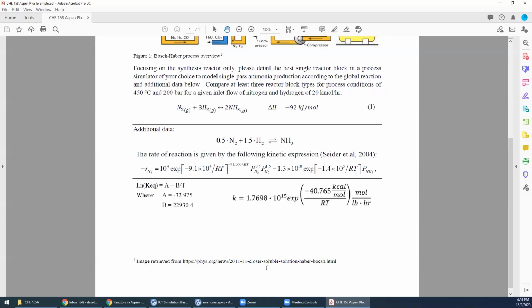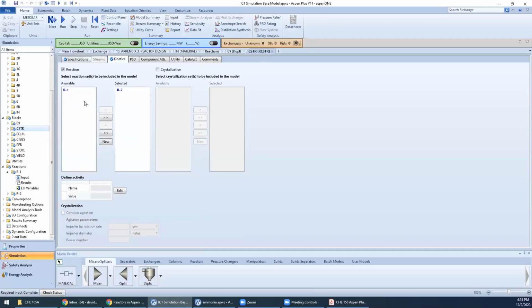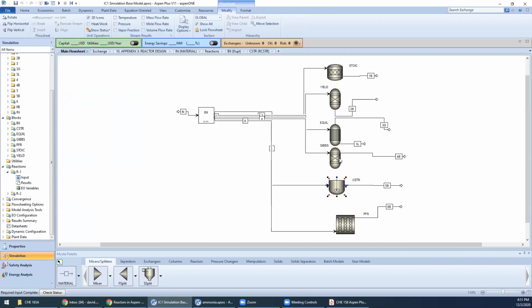Yeah. So the other ones, for example, the Gibbs, those are reaction models, right? Meaning they are not reactors, are they? Correct. It tells you whether the reaction will happen or not, how much will get converted, or what the temperature change is, something like that.